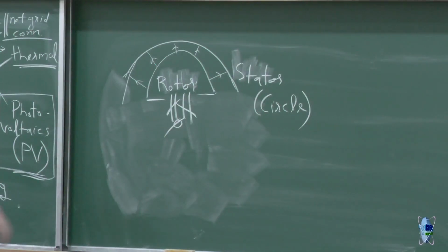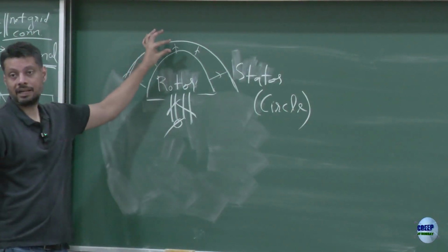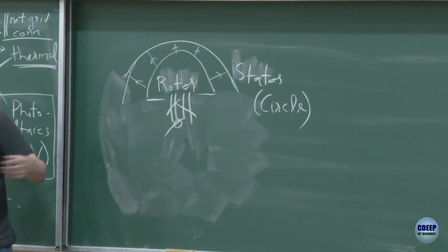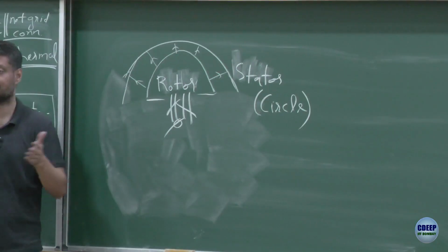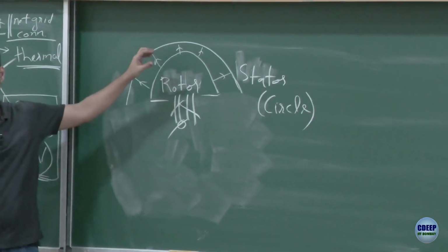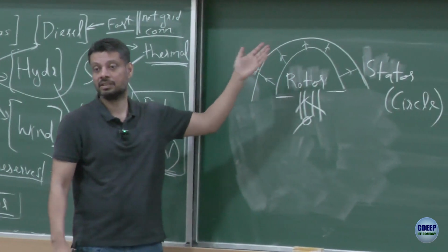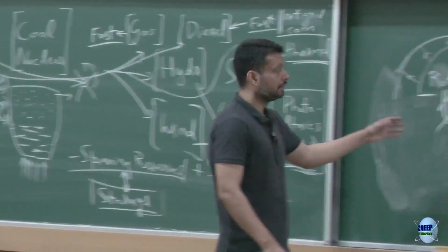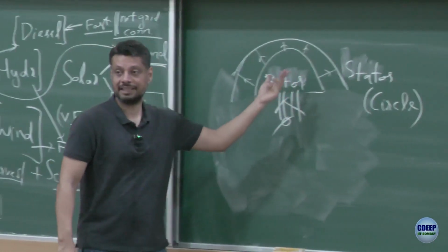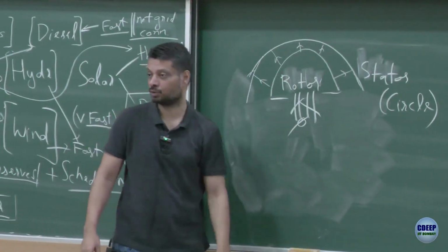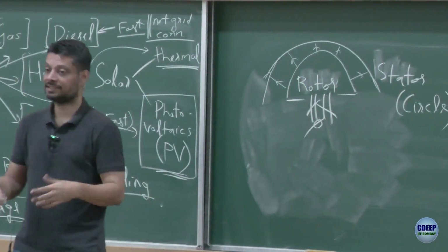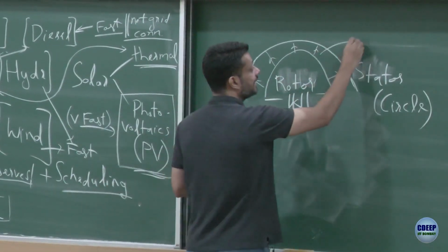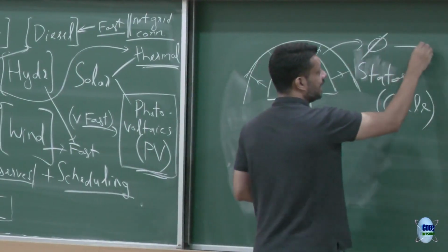No, right? Because here the reluctance is small, less, because of the lesser length of air gap. Here there is a larger length of air gap, so reluctance is more. A smaller air gap means more flux will flow through it, and a larger gap means less flux will flow through it. Now, if I somehow decide the shape of this, I can get a flux in the air gap which is